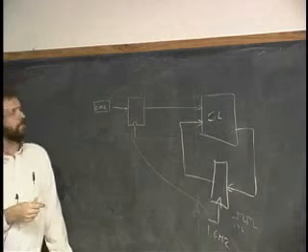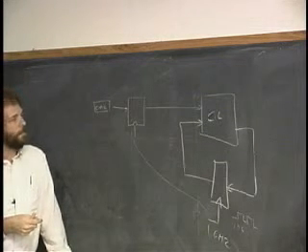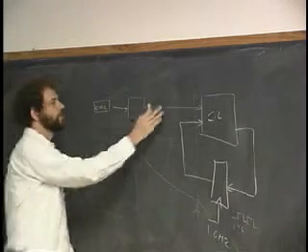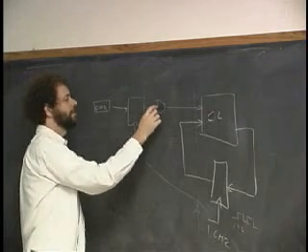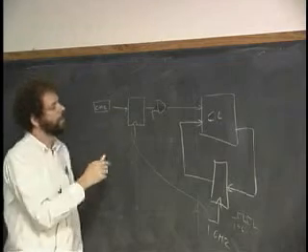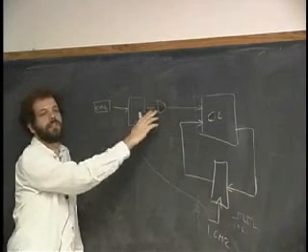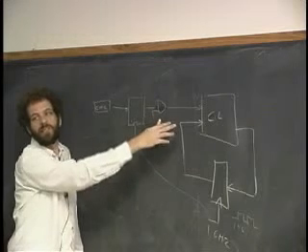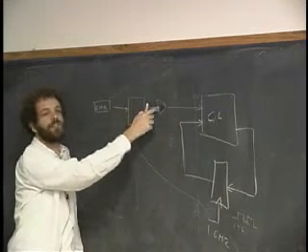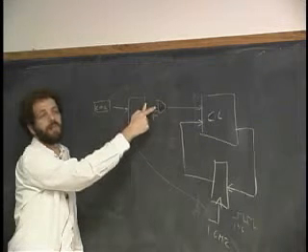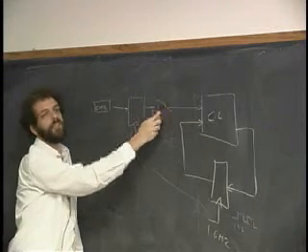Put a counter, it counts the clock cycles, and every 100 clock cycles it sends off a tick. Yeah, that's possible. So we could gate this and say every time we want to look at the input, disable this for 100 clock cycles before we actually take the value. And it turns out that AND gates are good at this. If this is a low, this could even be halfway between a low and a high, and this will still be a low.